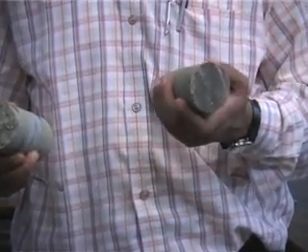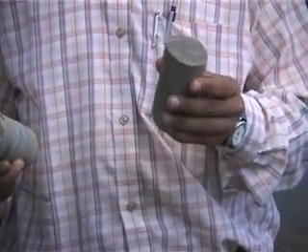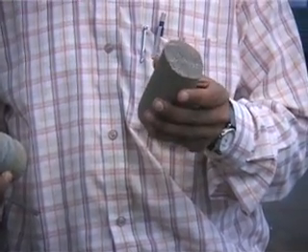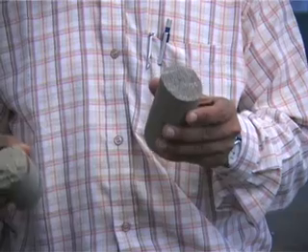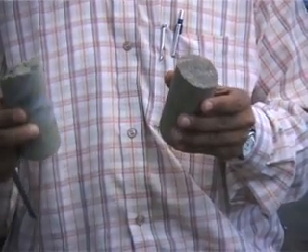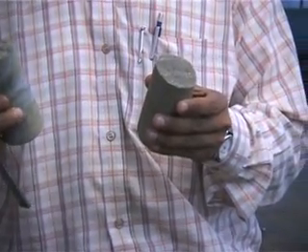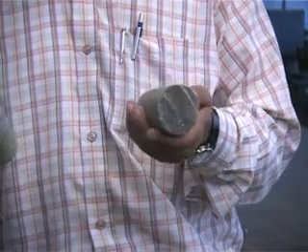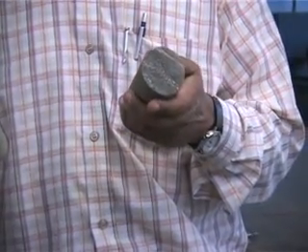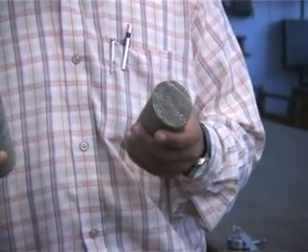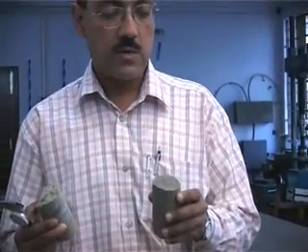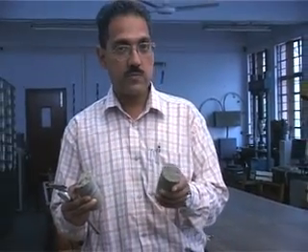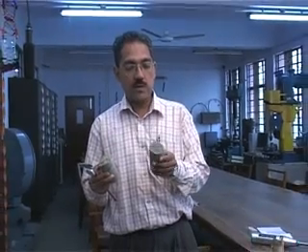What is also to be noted is that the samples we have chosen have a length of at least 1.5 times the diameter of the specimen. That is one of the requirements of point load testing. So if you recall, the point load index is point load divided by the square of the diameter of the sample, so we need to find out the diameter.